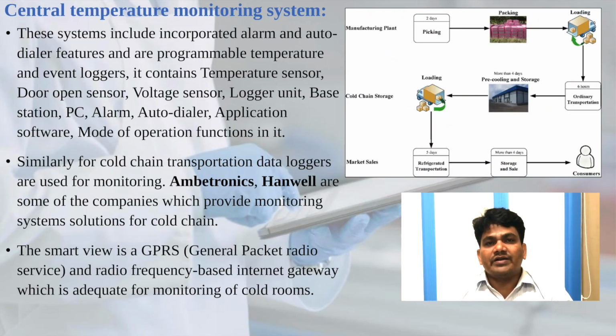Central temperature monitoring system, which is very crucial. These specific systems include incorporated alarm and auto dialer features, and programmable temperature and event loggers. It contains a temperature sensor, door open sensor, voltage sensors, logger unit, base station, PC, alarm, auto dialer, application software, and mode of operation functions in it.